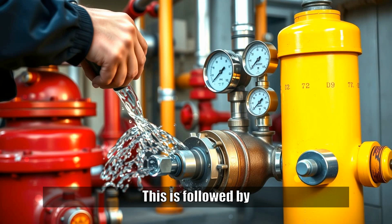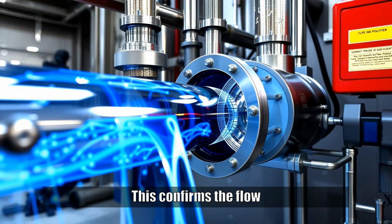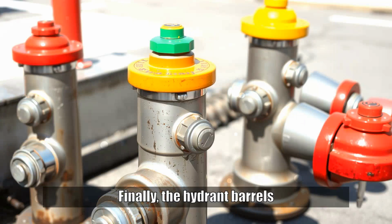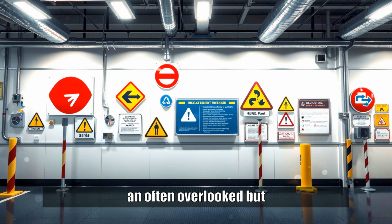This is followed by flow testing, where one hydrant is opened fully while pressure is measured at a nearby hydrant. This confirms the flow capacity and pressure integrity of the system. Flushing is performed to clear any debris, and chlorination may be applied if potable water contamination is a concern. Finally, the hydrant barrels are lubricated, caps are tightened, and the hydrants are painted according to the color coding scheme denoting their flow capacity. Signage and marking are an often overlooked but crucial part of the installation.